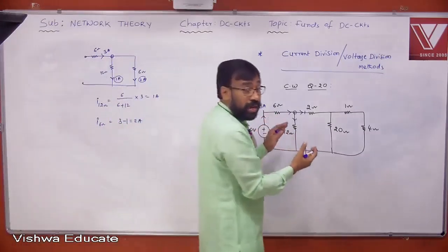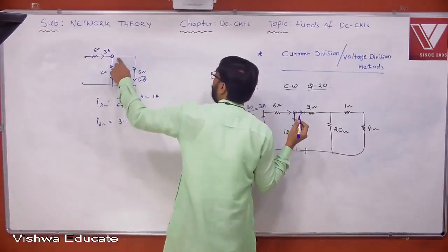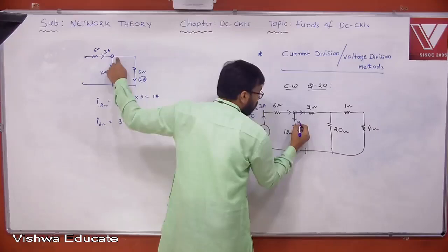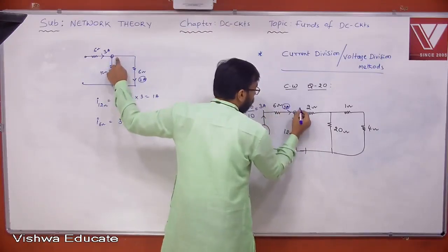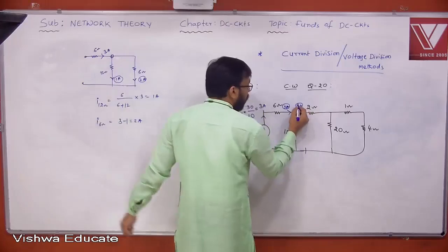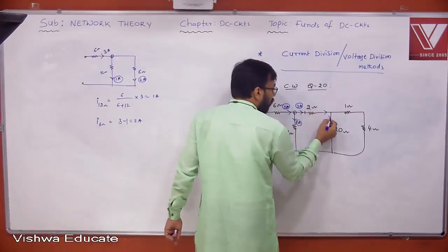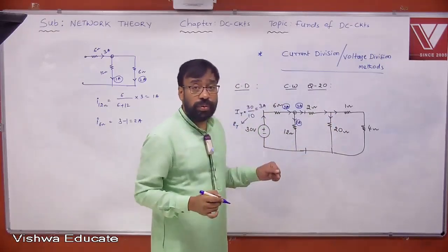You already understood that, okay? You already understood that the current flowing in this particular point, at this point means this point, right? So therefore this is 1 ampere and this is already 3 amperes. Then obviously here it is 2 amperes. Now this 2 amperes is actually flowing up to this point, the same current. Now it gets divided. Yes or no? Now it finds 2 paths.